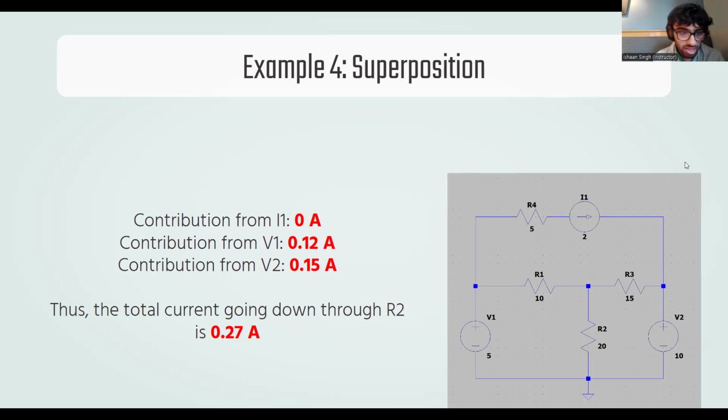Now, obviously, if we were to analyze the circuit from the get-go with nodal, find the node voltage right there, find the node voltage right there. If we were to analyze with mesh, look at this loop, and this loop, yes, that works. But in the lab, it's harder to measure mesh currents. And so actually, the best method that we have available to us is superposition and then also Thevenin and Norton circuits, which we'll talk about next time. So those are really the methods that you use when you're working with circuits in the real world.